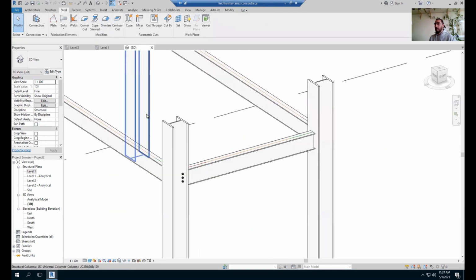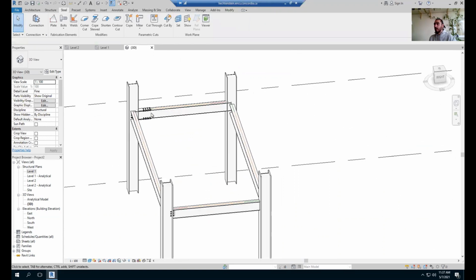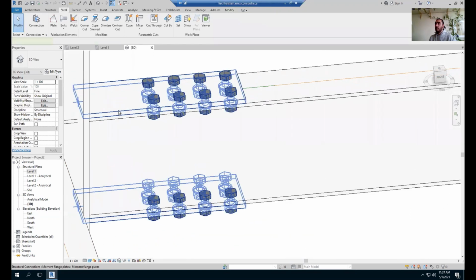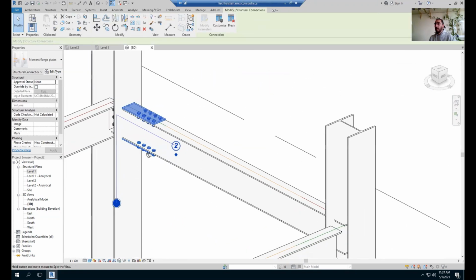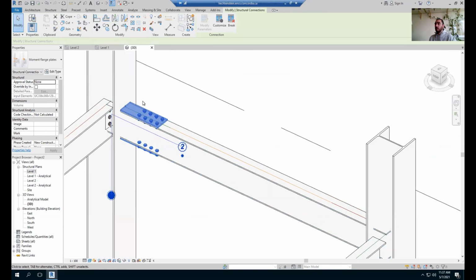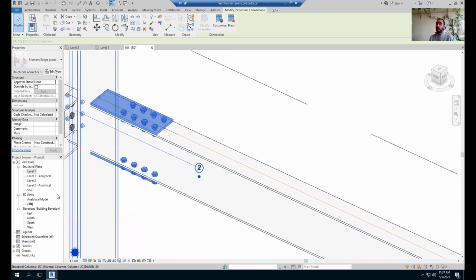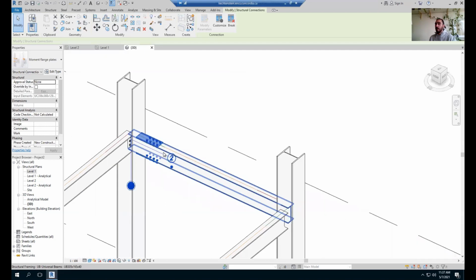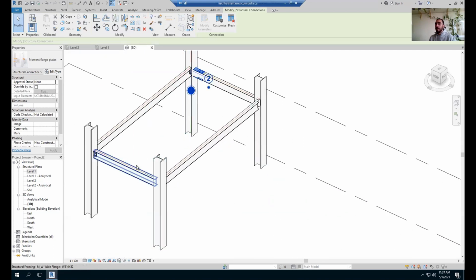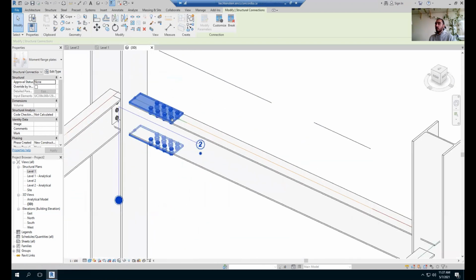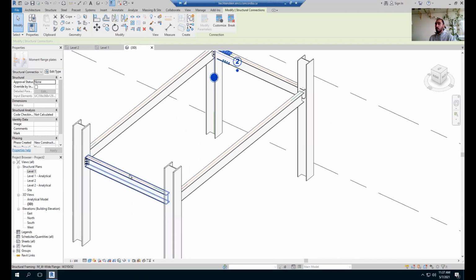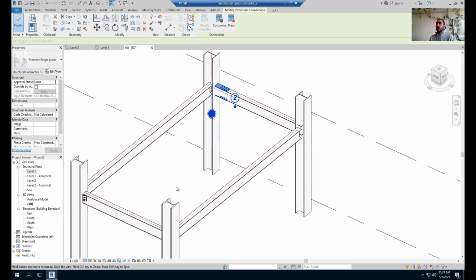If I get back on 3D, right, I'm having the moment framing connection there. So let me see if I can do the same thing the other way, on my M wide column and the wide flange beam that we've got there. So I can make some dimensions and then try to apply that here. It's pretty easy to make that connection. You guys will see that.